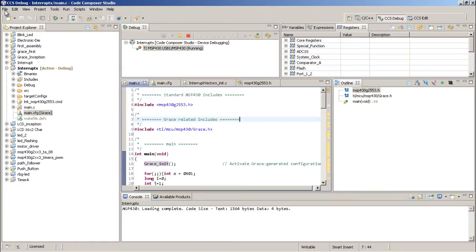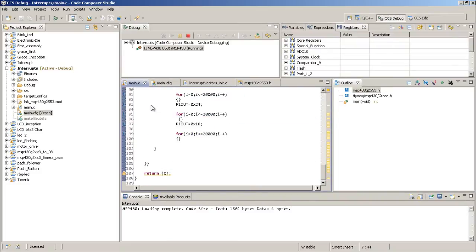Anyways, if you have not done that, you can use the good old breadboard. Connect the ports to a resistor connected to the positive of the LED, the negative of the LED grounded. Then once you have done that, you have to connect the switches. We'll come to the switch part later. First we'll start with the program.